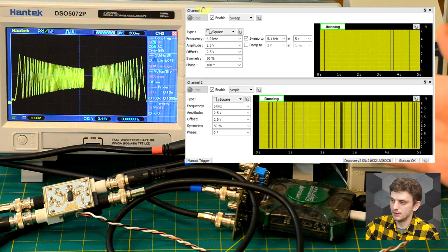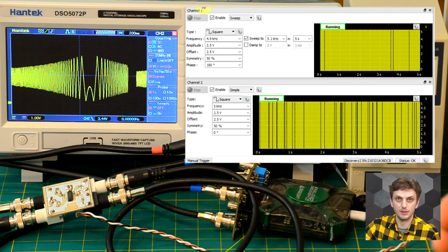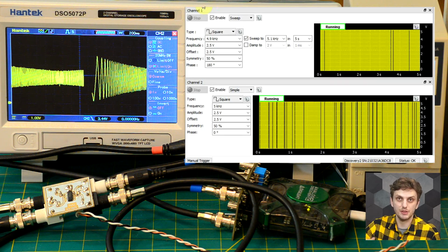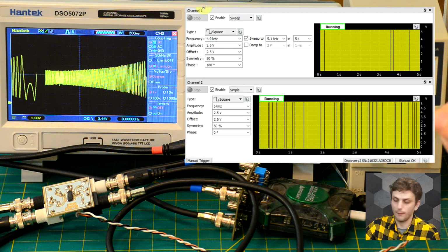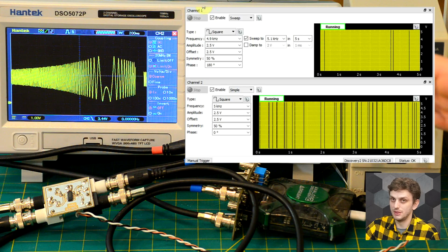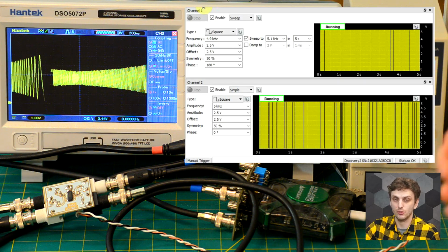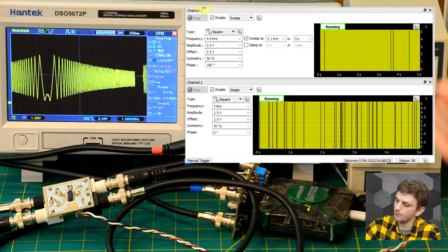So basically what this circuit is also doing is outputting the frequency difference of the two input signals. So in case they're at different frequencies, you will get the output frequency here. But you don't get a clear answer on whether this frequency difference is one way or the other. So if your reference signal is higher or lower frequency than the input signal.